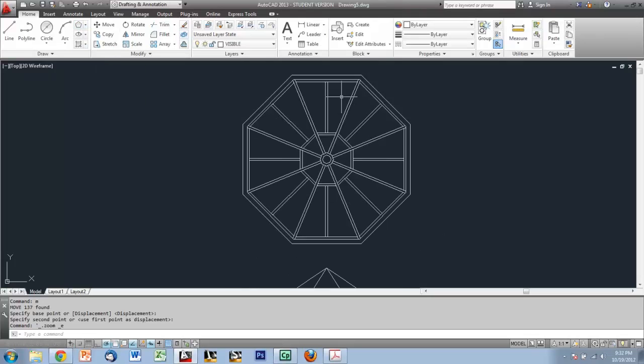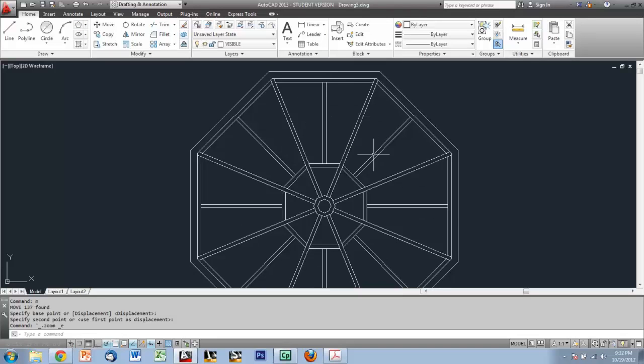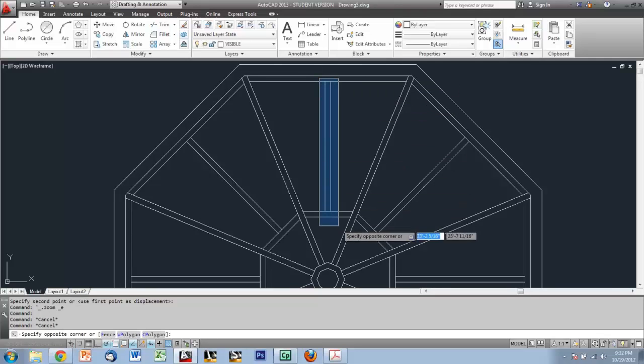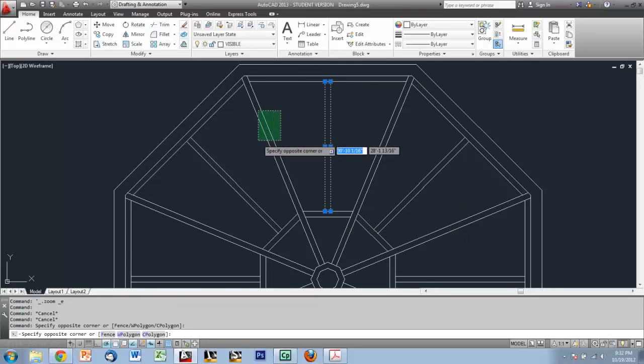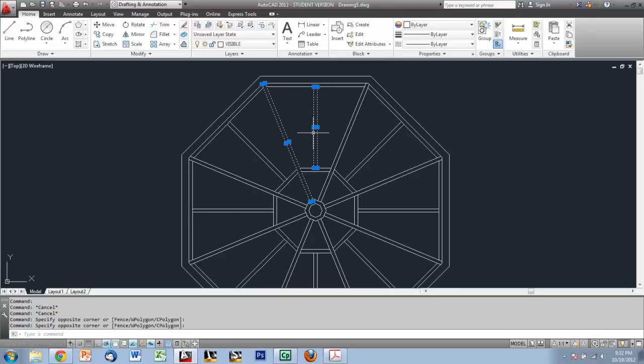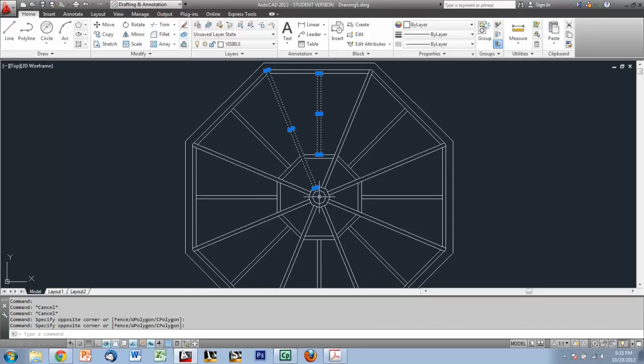And another tip is that when you create these 2x4s that go around the outside to create the roof framing, what you want to do is draw this top one here. So you'll draw that one, and then you want to draw one of these also that's at the longer length. And you'll take those two and make sure you have them trimmed appropriately before you do this. But you're going to create a polar array using the center of the gazebo roof as your center point for that polar array. So you'll select these two and array them around together, and that's going to keep you from having to do a lot of trimming.